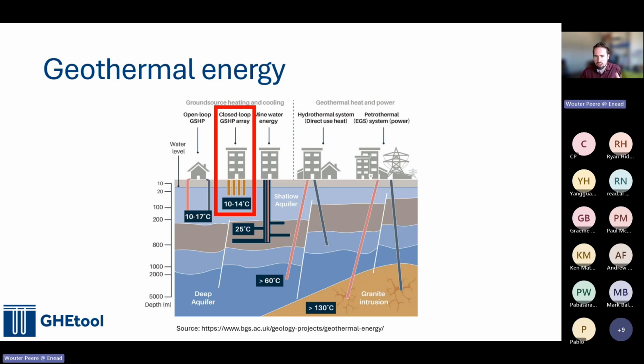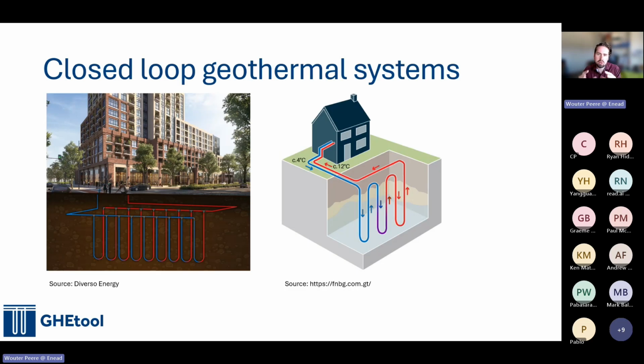Now, this type of technology is very flexible. It can be used for residential houses, and for commercial and office buildings. Basically, you drill a hole 150 millimeters in diameter, or sometimes smaller, 100 meters deep. You put in a heat exchanger, you connect everything to your building, and by letting the fluid circulate through these pipes, you can exchange heat with the underground. So it's a shallow system, it's a heat battery, and I will call it borefields or BTES systems. It's also sometimes called by other names.